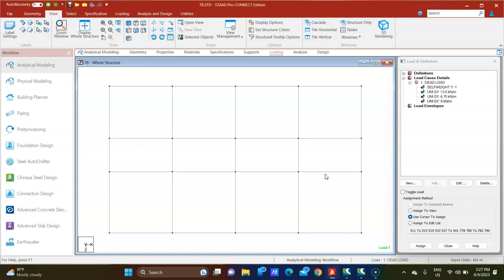I told you that the thickness of the lift RCC wall, you should provide 150 to 200. How much are you comfortable? So 200. Right? For 200 mm RCC wall, that load has to be put, because we are not modeling the RCC wall.